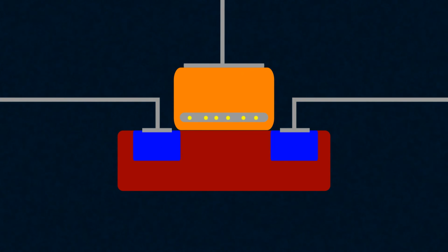And what's remarkable is that our floating gate is isolated from other parts of the cell. And to influence the number of electrons in it, we need to apply significant voltages by the standards of microelectronics. And if such voltages are not applied, then there is simply nowhere for the electrons from the floating gate to go, which means that the cell will retain the information written in it even when power is turned off. That is, the memory created based on such cells will be non-volatile.